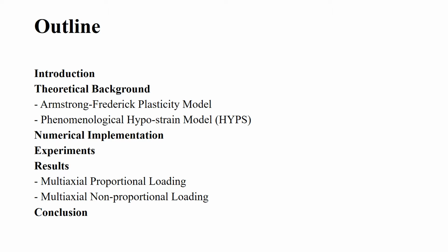On theoretical background, I will talk about a widely used constitutive model, the Armstrong-Frederick plasticity model, and a new phenomenological model called Ipostrain to describe the cyclic elastic plastic behavior of magnesium alloys. Later, I will present the numerical implementation, the experimental tests, the results, and finally draw the main conclusions.